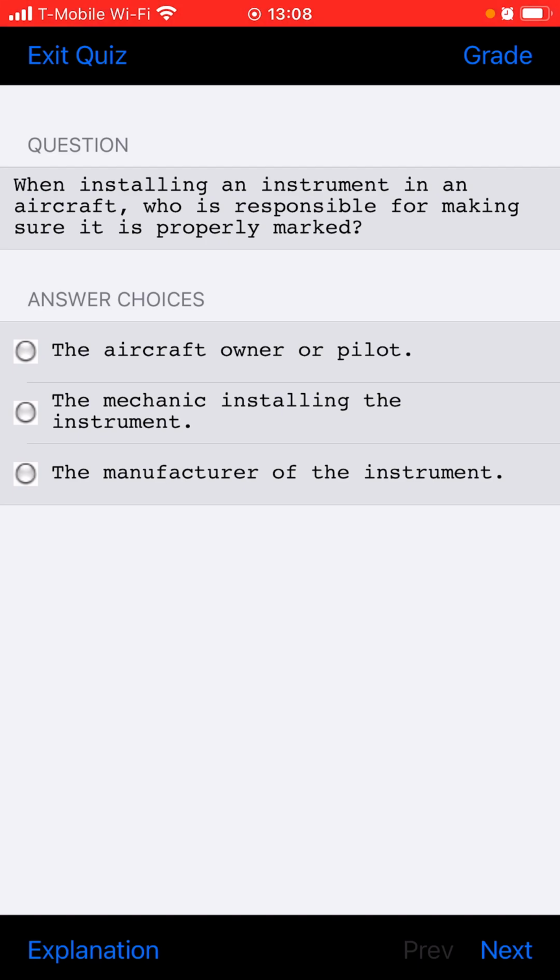Name at least two conditions that would activate the takeoff configuration warning system in a jet transport aircraft. Incorrect leading or trailing edge flap position, stabilizer position, or speed brake not stowed. The manufacturer may establish other conditions.